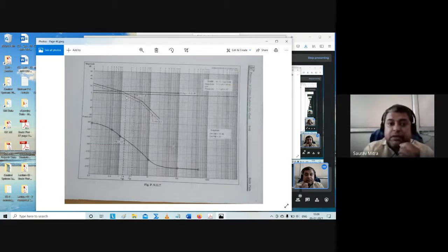So again I'll repeat the process. First step, you found the resultant amplitude, then you draw the phase, and then you dropped this omega GC below onto the phase line. Okay, and you find that at omega GC of 1.4 radian per second the system phase is minus 165 degrees, which is plus 15 degrees, or 15 degrees above the minus 180-degree line. So your logic is, at gain crossover the phase margin is positive. That means the system is stable.